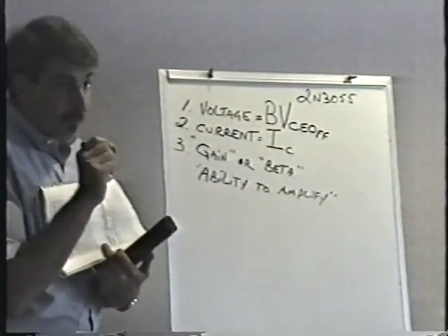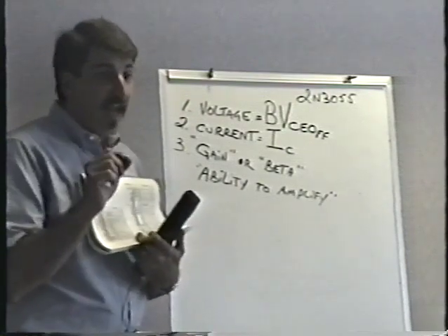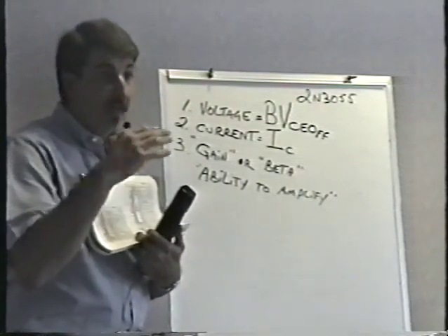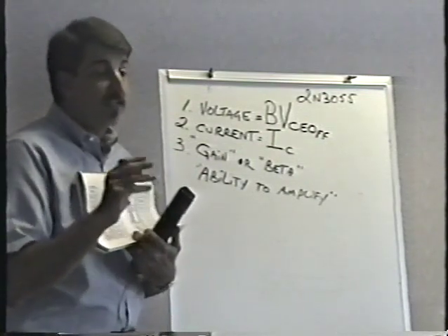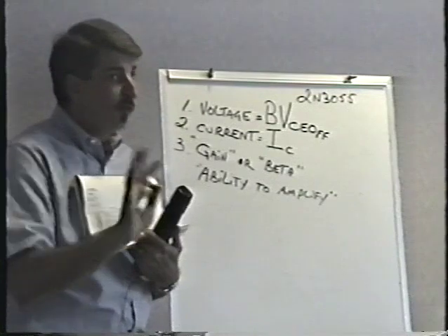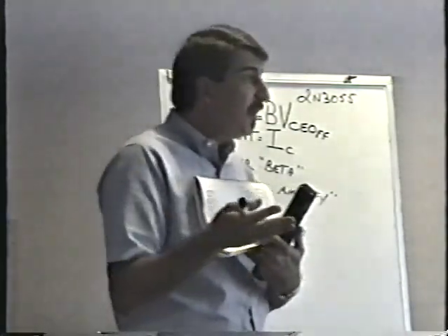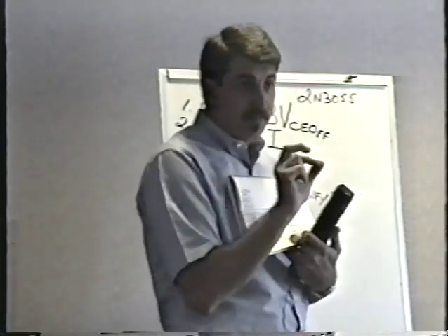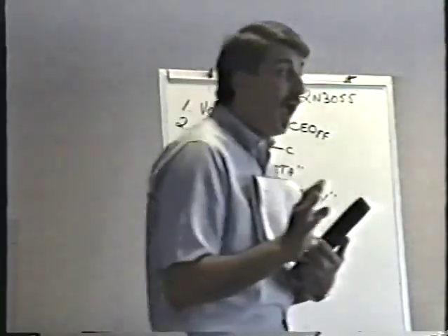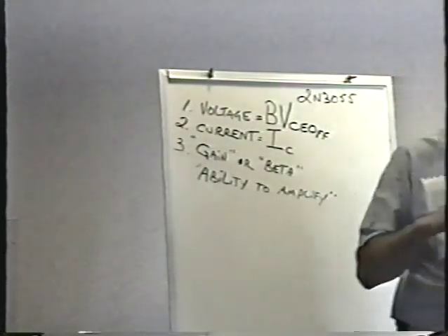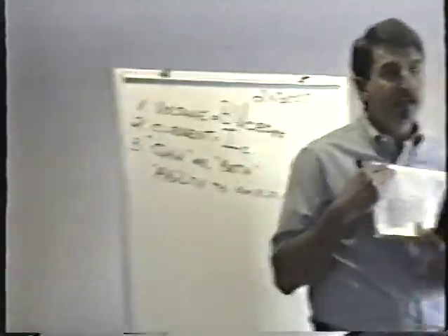This is the same part with the same specifications, same voltage, current, and all that, but opposite polarity. It's PNP instead of NPN. It's called a complementary pair. You don't really have to know that, but it's two transistors with the exact same specifications and opposite polarities. They are not interchangeable in any way. You can never interchange an NPN for a PNP under any circumstances.